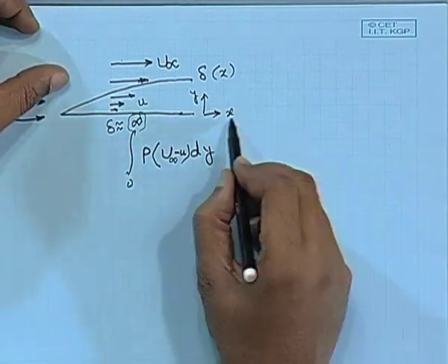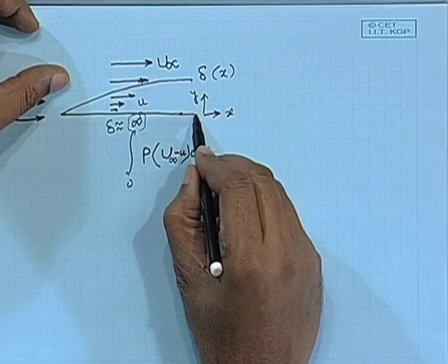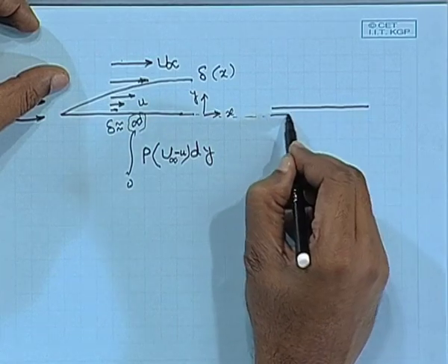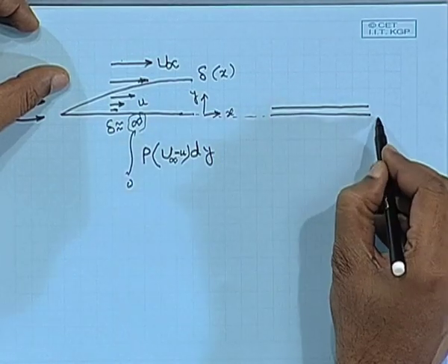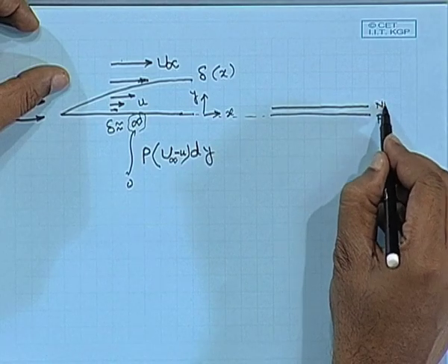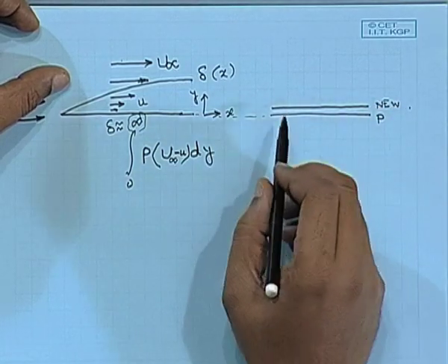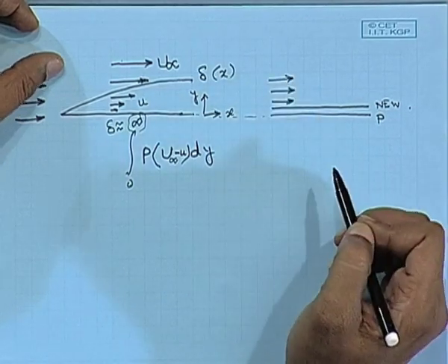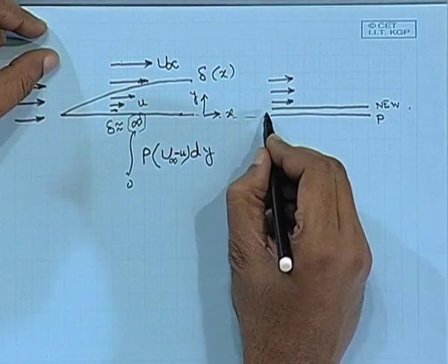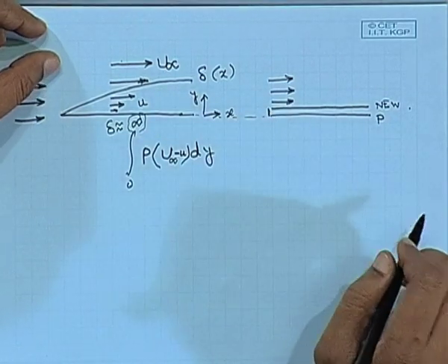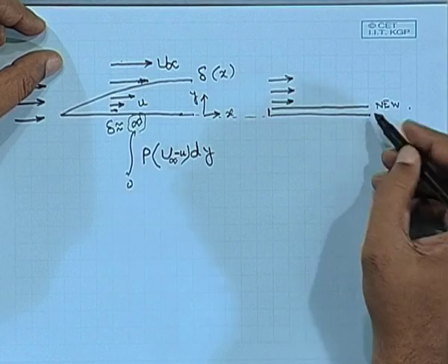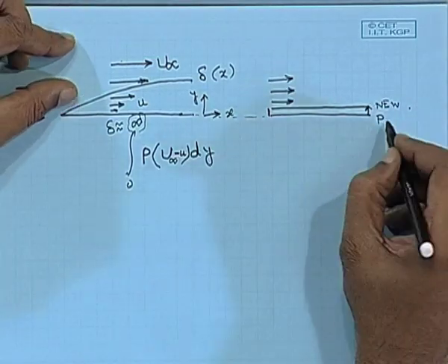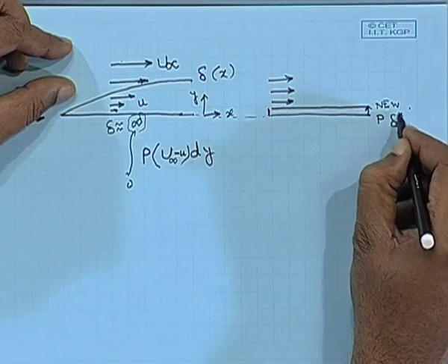Now, you would like to do it in a different way. Instead of keeping the solid plate over here, you have moved it up by some distance. So, this was the previous position and this is the new position. Let us assume that the flow here now is inviscid. That means there is no viscosity, but this much area is unavailable to the liquid now, since you have moved it up by some distance. Let us call that delta star.